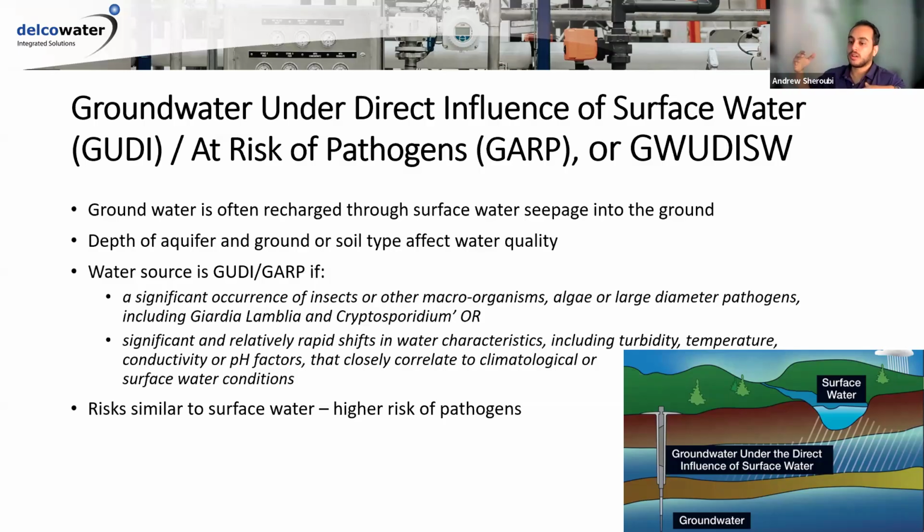However, as the water moves through the ground, it also has the opportunity to attract or dissolve minerals. So we see some generalized characteristics of groundwater: it's low in turbidity because particles got captured by the soil, but high in dissolved constituents like metals and minerals.